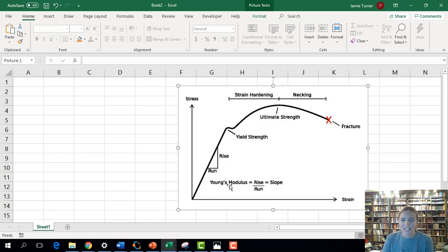You want to see it bending and struggling and say, the bridge is going to break before it actually goes. You want a lot of warning. And so somewhere in between those two extremes of brittle versus really ductile and elastic gives you your best materials. And there's a whole science in metallurgy of how to develop alloys and heat treatments that will give you the strength properties that you want in a material.